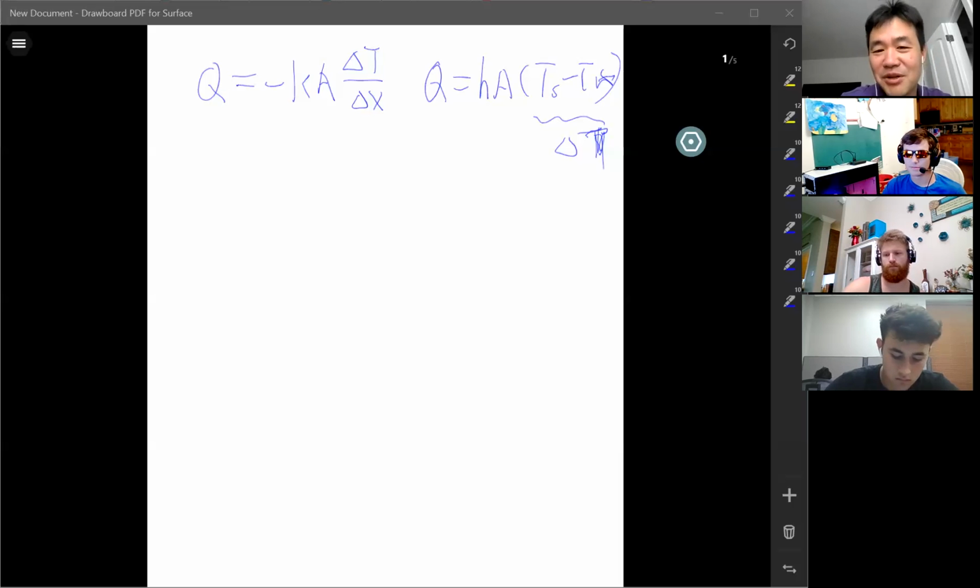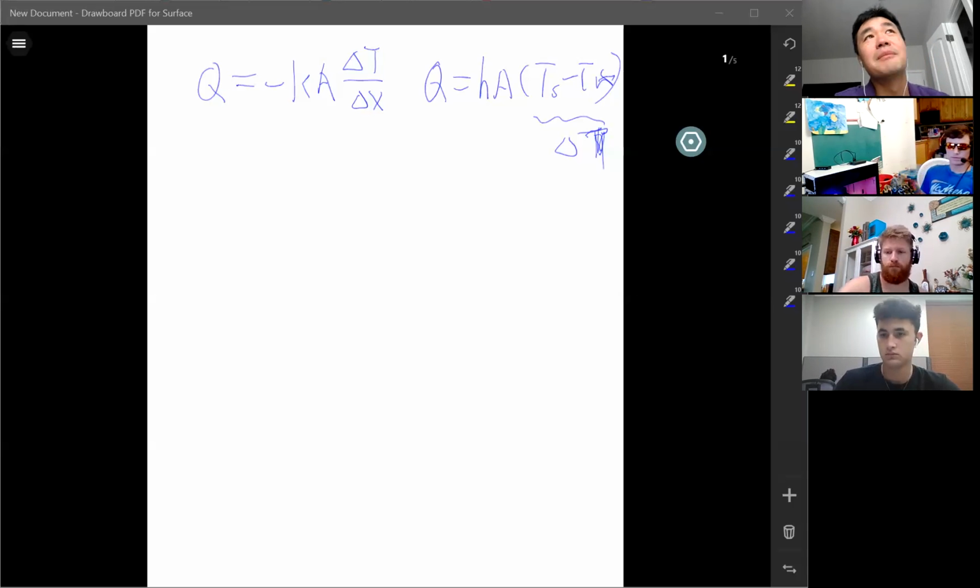Based on that equation, there's no delta T. Your ambient temperature is the same as your body temperature, so there won't be any heat transfer happening, even if you turn on the fan and blow air to you. It doesn't help. Be careful on this. Sometimes you don't have heat transfer. If you don't have heat transfer, you won't feel any cooler or any more comfortable.